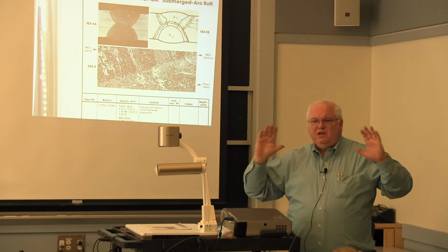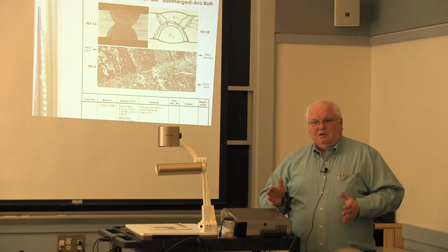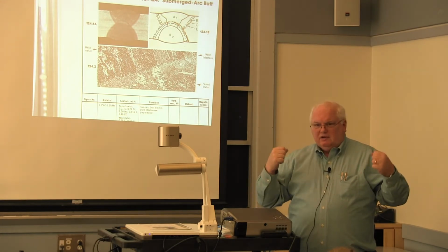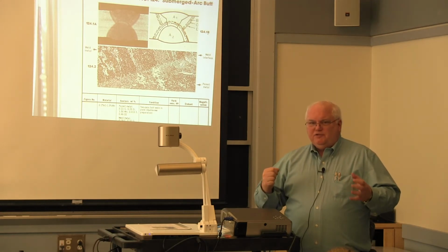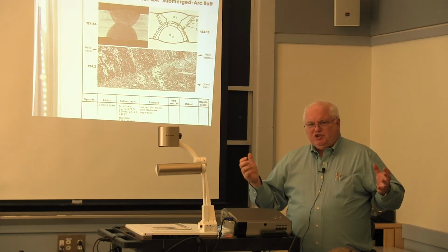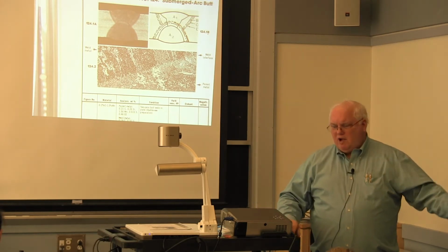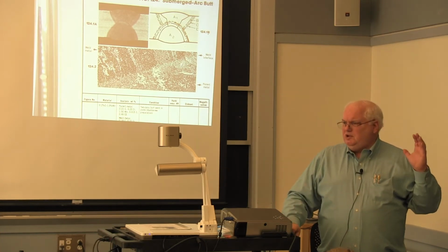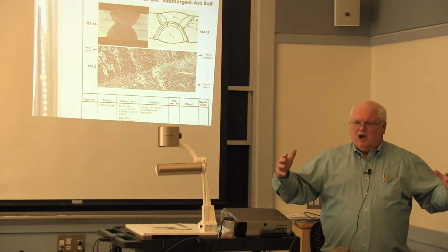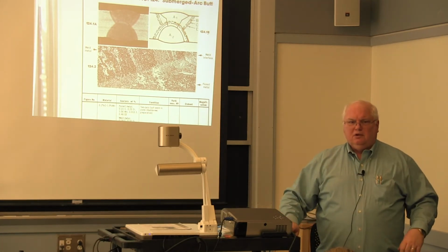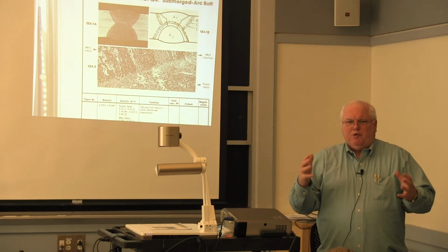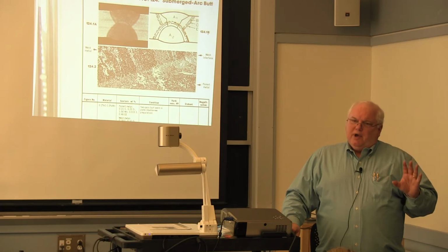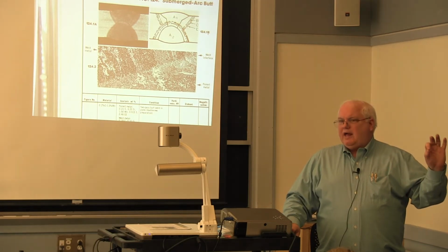You could save millions of dollars on your preheating cost, but every time they've done it, they've done the fracture, and you have to weld up whole structures and shoot at them with ballistics if you're the Navy, put them in great big testing machines at Lehigh University or out in Boulder, Colorado at the National Institute of Standards and Technology, where they have these multi-million-pound test machines, things you can put a huge I-beam in and just tear it in two, okay? You can take a whole structure panel from a bridge and you can bend it and tear it apart. With undermatching weld metal, you concentrate the strain at the weld.